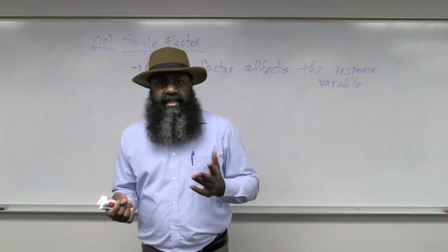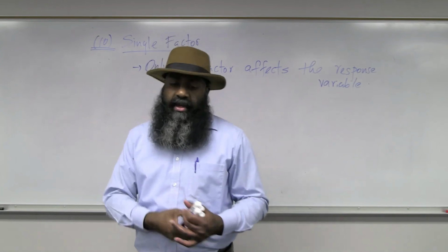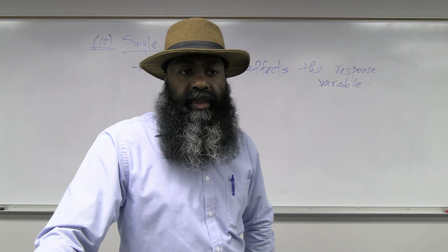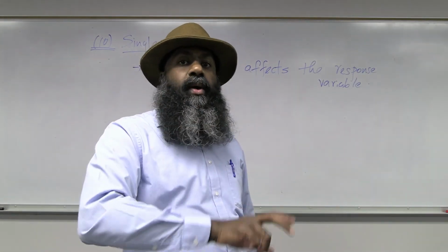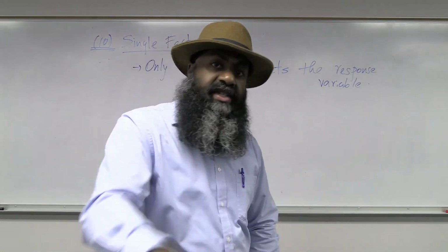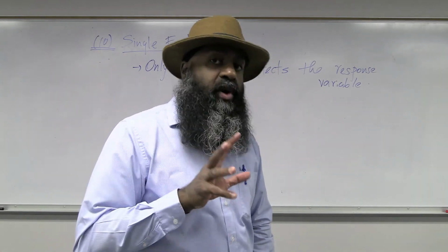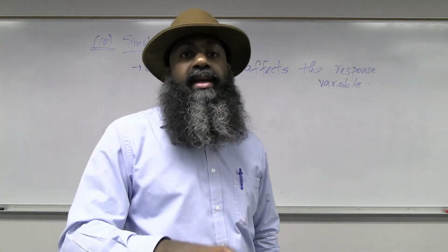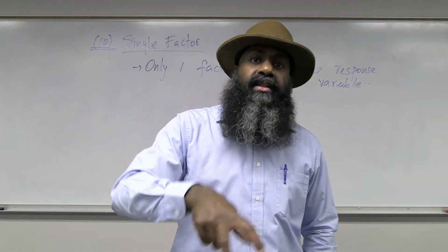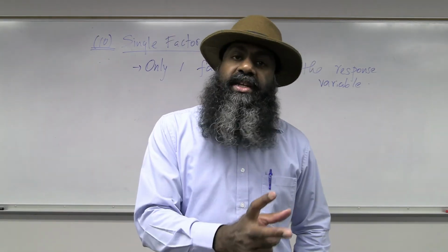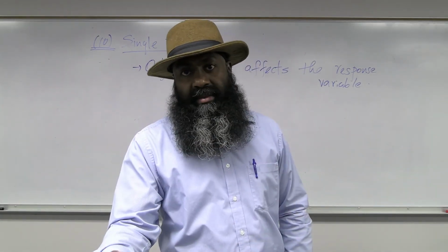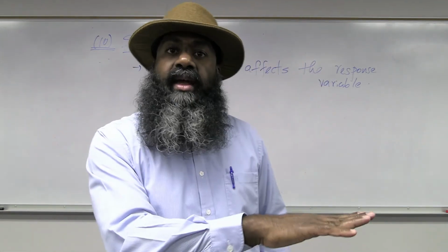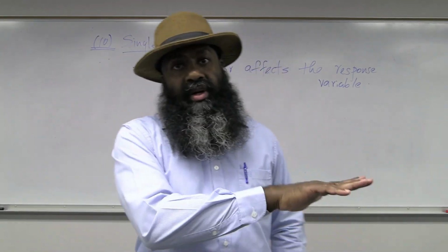How about the other things, such as the temperature? As you do the milling operation, the temperature increases in the workpiece. Can I allow temperature to affect the surface roughness? Well, if I'm going to arrange it as a single factor experiment, I should not allow any other factor to affect the response variable. That means temperature should not affect the response variable. So in that case, I will have to use coolant and make sure that temperature is maintained at exactly the same rate throughout the entire experiment.